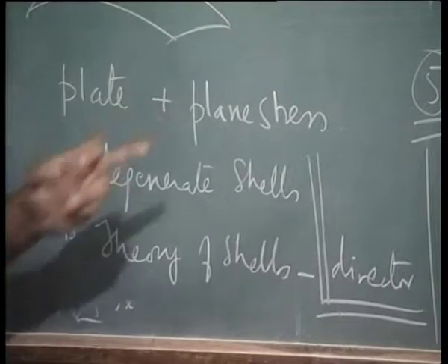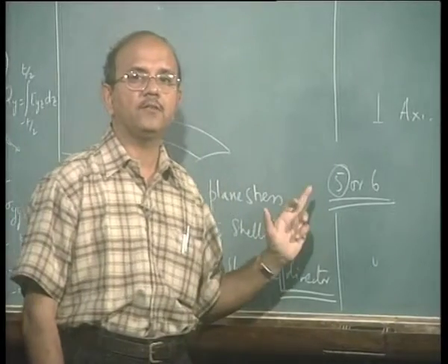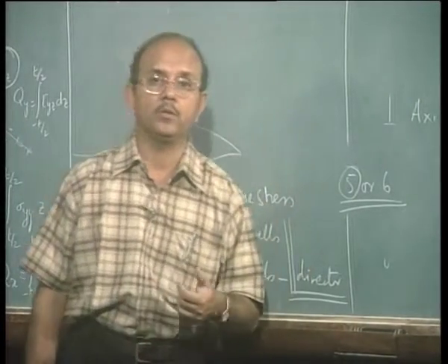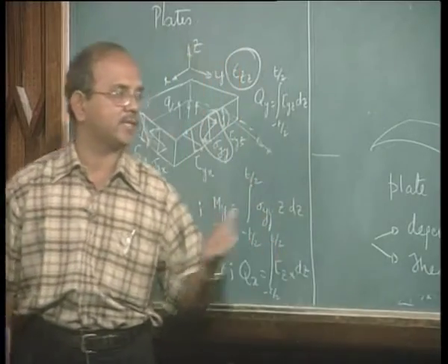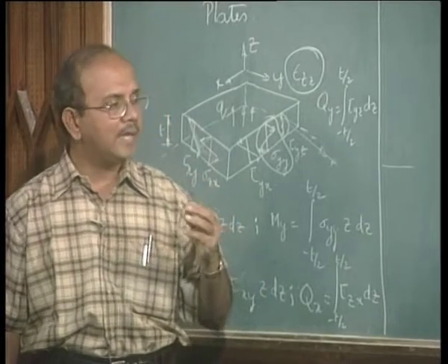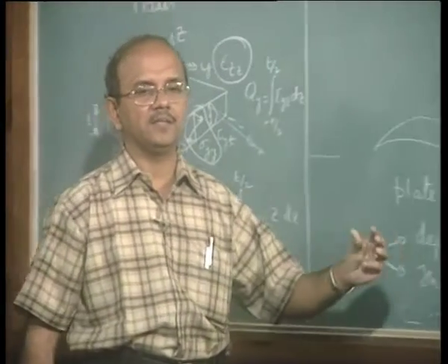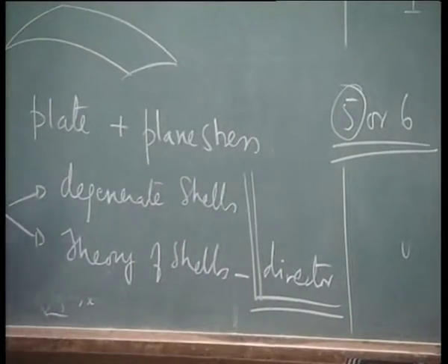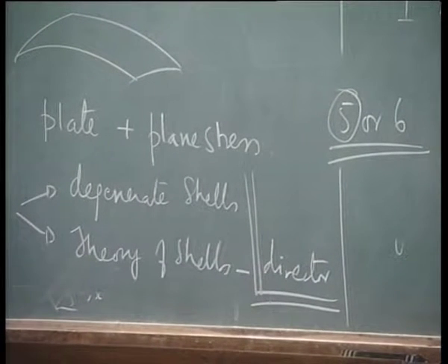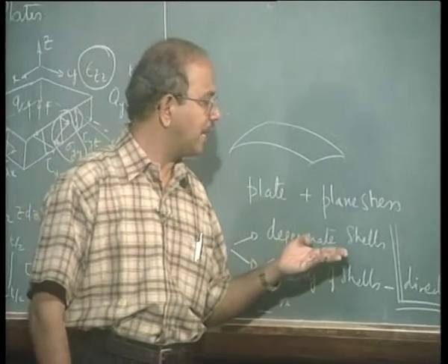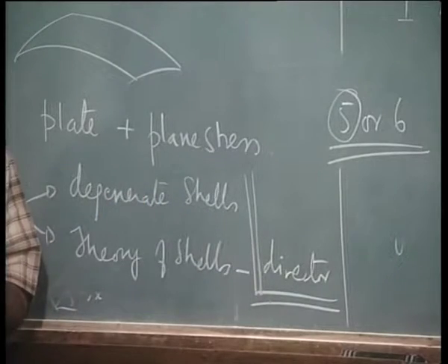For example, if the formulation is based on theory of shells, then the 5 degrees of freedom may not be the degrees of freedom with which you are familiar. These may of course be displacements in the x, y and z directions. The other 2 degrees of freedom are not pure rotations; they are related to the director theory. On the other hand, in order to make it palatable, to push a lot of problems under the carpet, many of the softwares have 6 degrees of freedom, and that is through what we call the degenerated shell.